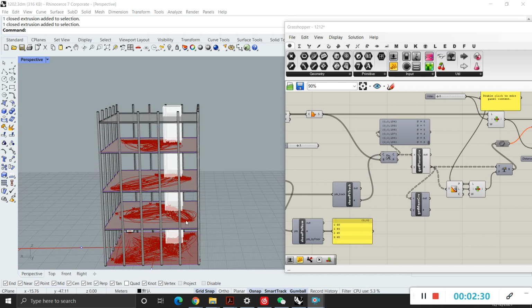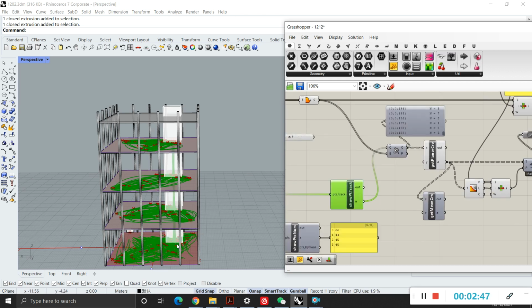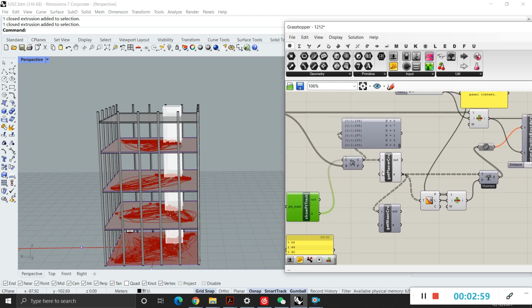After it reaches a stable state, we pause it, and here are two components. I wrote them to show the tracks and also the speed of those tracks on each floor. This one will show the tracks of each agent, and as you can see, there are lots of redundant curves in the elevator areas. And also I wrote another one to clean those vertical curves and only keep the horizontal curves on each floor.